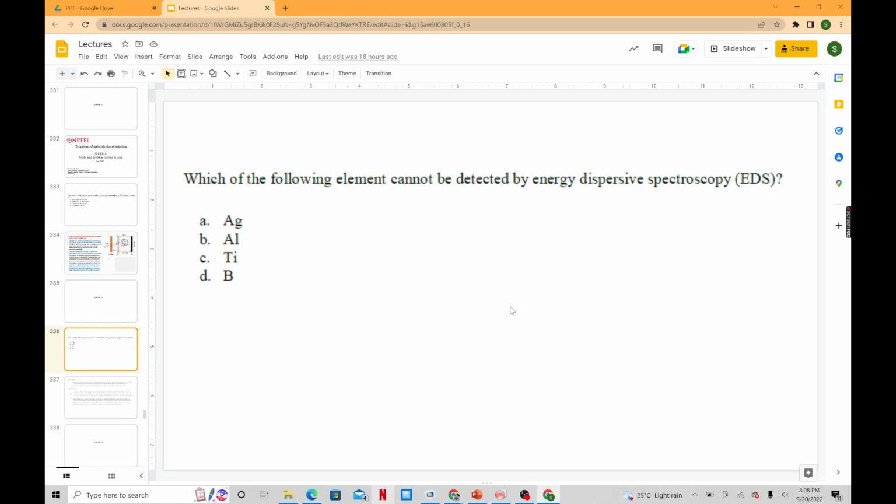It is said that by using a polymer in the window there is a possibility of detection, but they cannot assure it. Even if you can detect, you cannot detect the exact composition, so you will not have much surety. Although it is said that you can detect, it will always be preferable to note that for light elements, it will be difficult to detect by EDS.